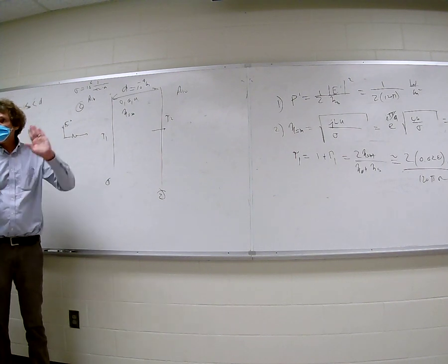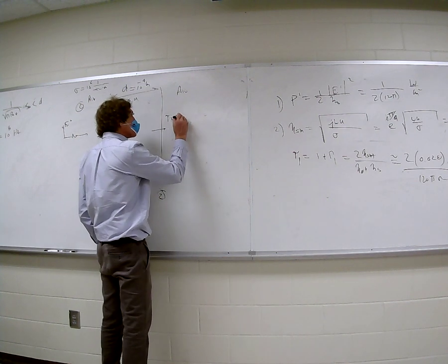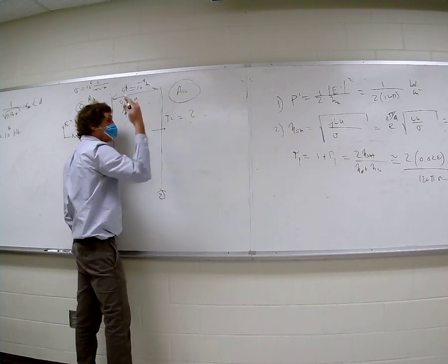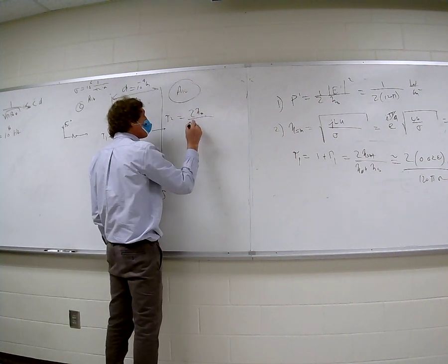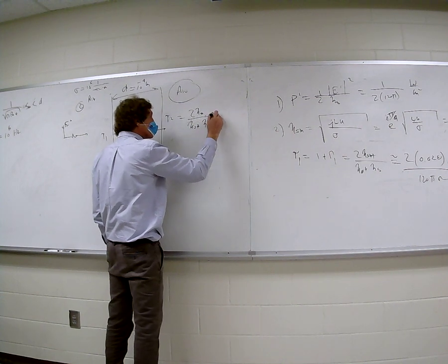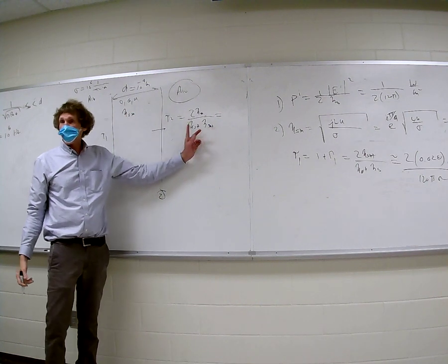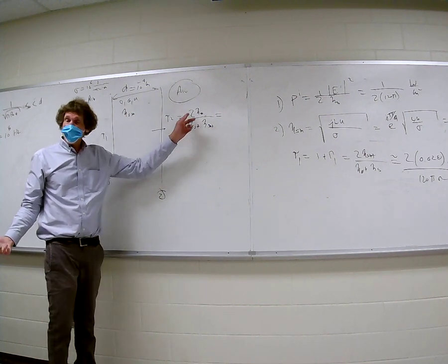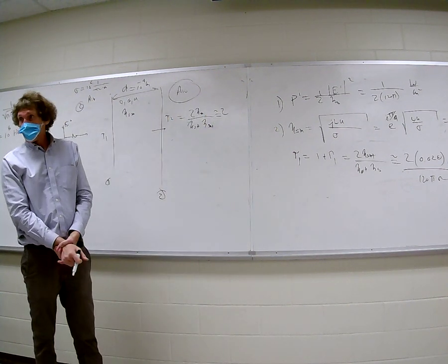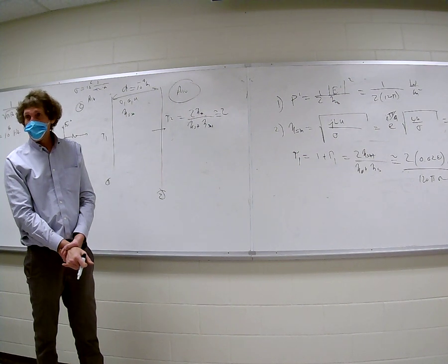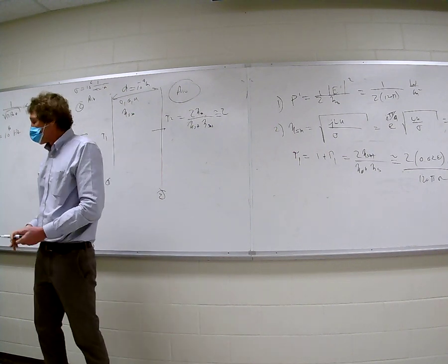What is that always? The impedance you're going into times 2, right? So that's going to be equal to 2, what's the impedance out here? Eta naught, right? 2 eta naught over eta naught plus eta shield. Does everybody see that this is about 2? Because eta shield is so small. You add eta naught to it, it's about eta naught. So the eta naughts cancel. And this is about 2, correct? I want to make sure you see this point. Right? Now, be with me on this part.